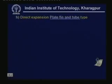Next, let us look at the direct expansion plate fin and tube type evaporator. As the name implies, the plate fin and tube type evaporator is constructionally similar to the plate fin and tube type condenser, okay. So here the external fluid is air, right. In the case of a condenser also, the external fluid is air and the refrigerant flows through the tubes. So in the plate fin and tube type evaporator also, the refrigerant flows through the tubes while the air flows outside the tubes, okay.